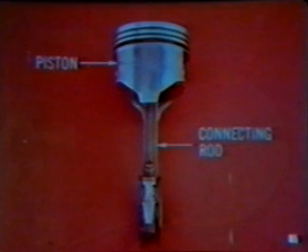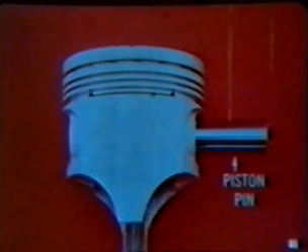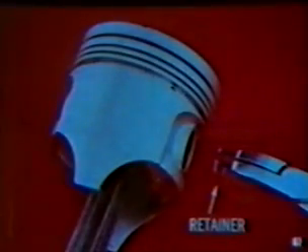Now let's go on to describe the piston and connecting rod assembly, which would be the next installation after the crankshaft. A steel piston pin, sometimes called the wrist pin, connects the rod to the piston. This pin must be free to turn in either the piston or the rod, so that the rod can rock back and forth as the crank turns. In some engines, the pin turns freely in both the piston and rod and has retainers at both ends to keep it from sliding out.